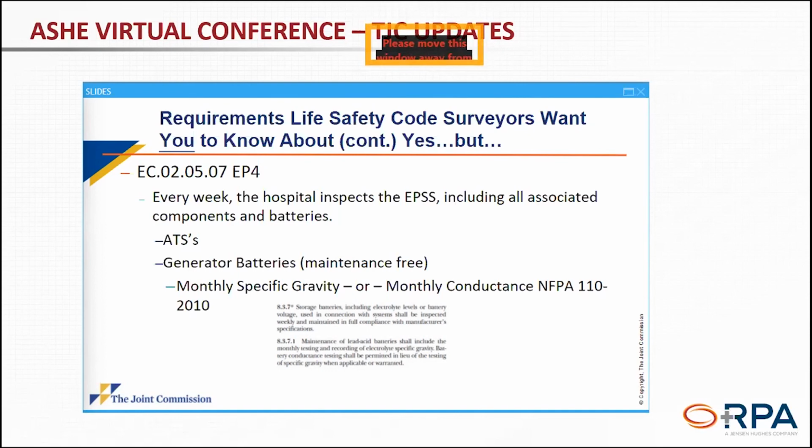So that means taking a tester and making sure conductivity is being maintained. And it's not an involved test, but you want to make sure you're doing it, because those maintenance-free batteries are not totally maintenance-free.